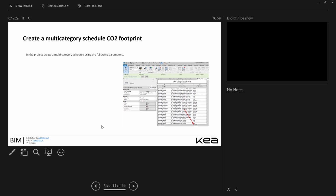But isn't the CO2 footprint the same no matter how much the amount is? It's still going to be 402 per. No, but because here we have a composed element made of two materials. Yes, but the wood part is still going to have minus 1000. Yes, but you need to schedule it. You cannot schedule it separately in Revit. You can schedule by element, and normally by element, by default, we have a column of concrete or a column of wood. We don't have a column of concrete and wood, right?